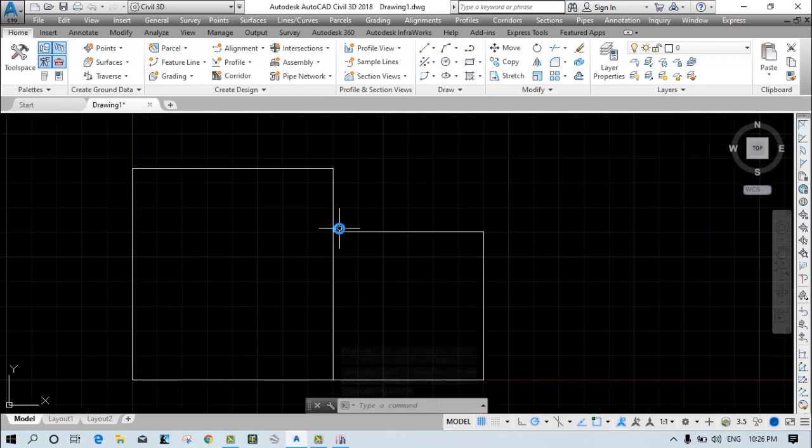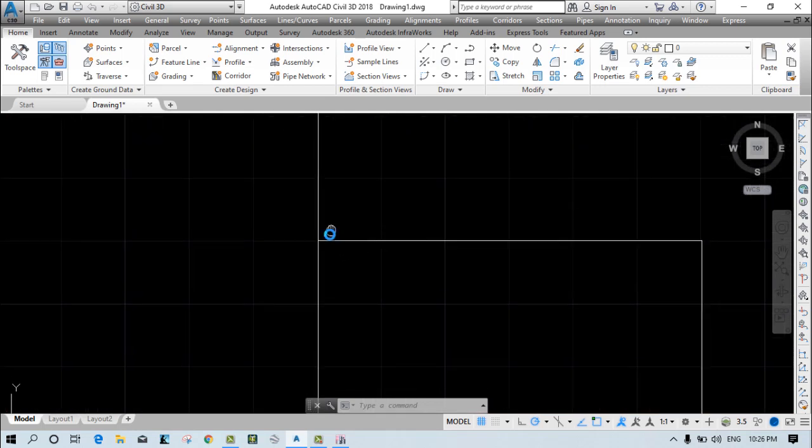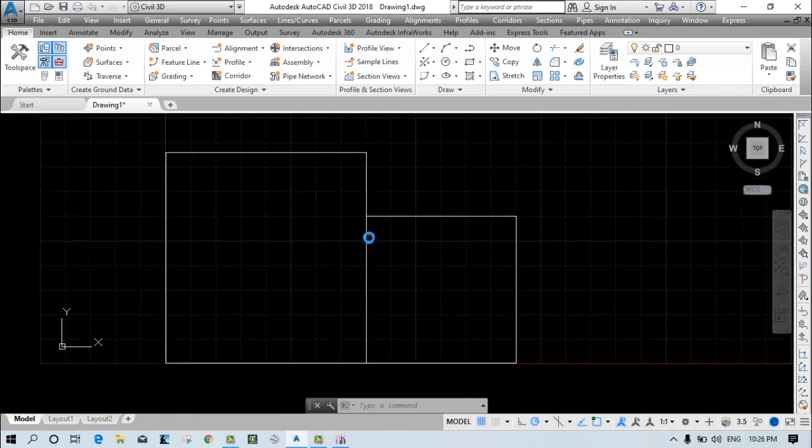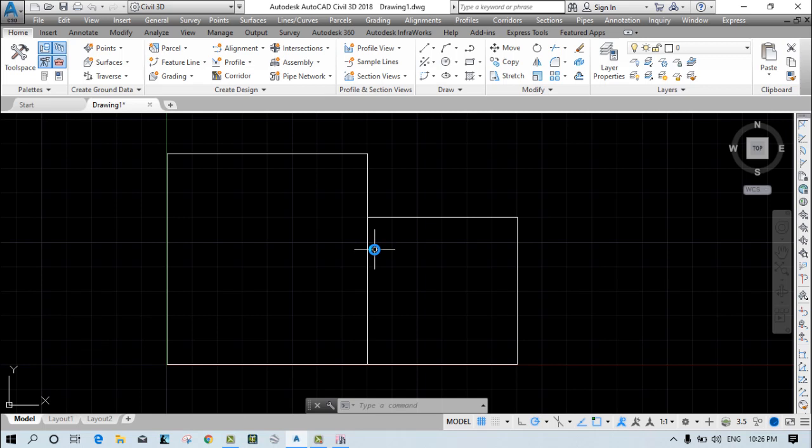Okay, now why I'm telling you to break this beam? Because in STAAD Pro or in ETABS, whenever you are going to apply the live load, the slab load, the two-way dispersion will be there definitely, right? There will be the two-way dispersion, like one triangle and one trapezoidal, right?